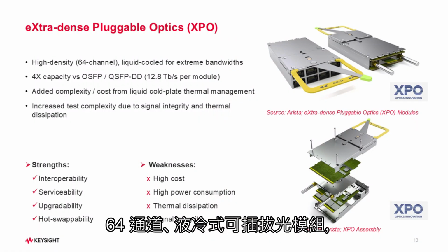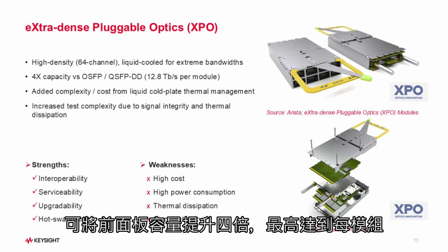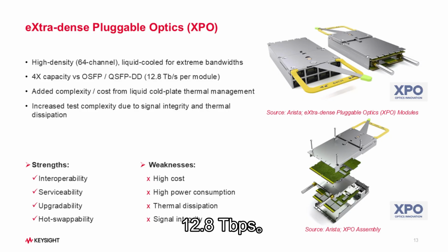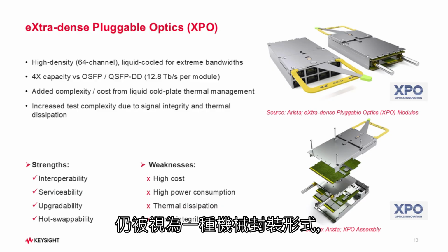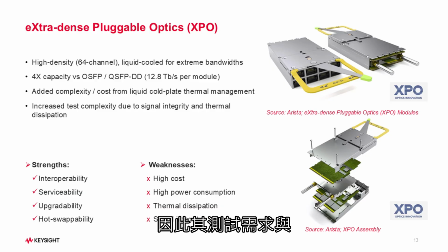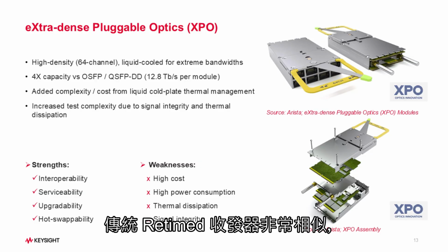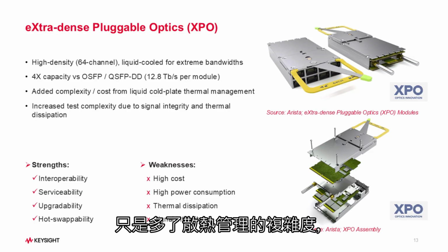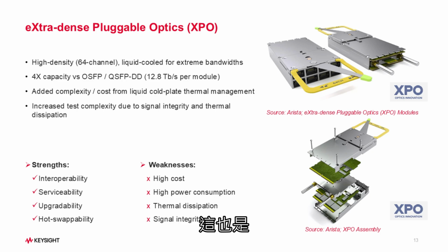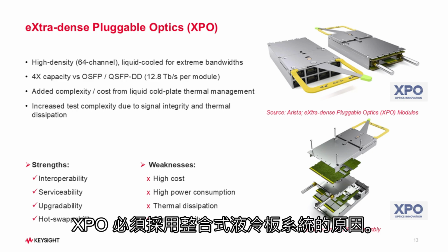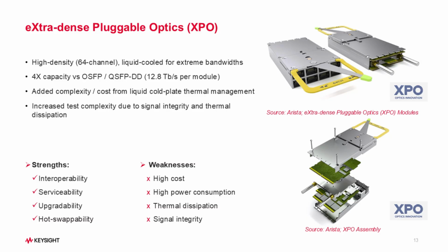So the XPO is a high density 64 channel liquid cooled pluggable optical module that quadruples the front panel capacity up to 12.8 terabit per second per module. Having that being said, XPO is largely considered a mechanical form factor. So the test requirements for XPO are very similar to those of classical retime transceiver, with the added complexity of thermal dissipation, which is the reason why XPO relies on integrated liquid cold plate systems.